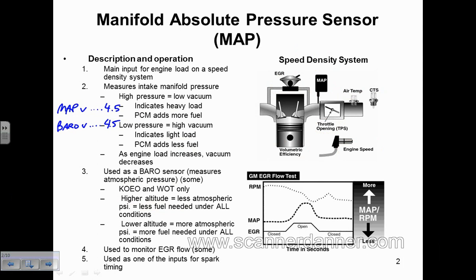And so looking at that, if you didn't know, you would think you have a separate BARO sensor. You don't. Where's that number coming from for the BARO? From the MAP directly. Then you start the car, and this one's going to drop to around 1 to 1.5 volts at idle. This one stays stationary. That one doesn't move. So you're driving your car, your BARO numbers, whatever. What you guys need to understand is the computer adjusts the entire air-fuel ratio based on this BARO signal.